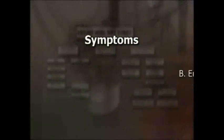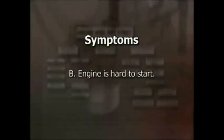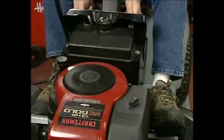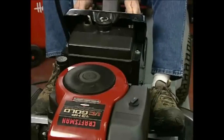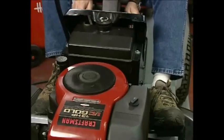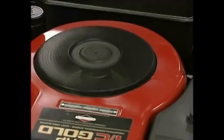Now let's go back to symptom B. The engine is hard to start. A choke-style carburetor exhibits harder starting when the high-speed air circuit is clogged. The high-speed air bleed acts as a vent to allow the fuel to be drawn up the emulsion tube.